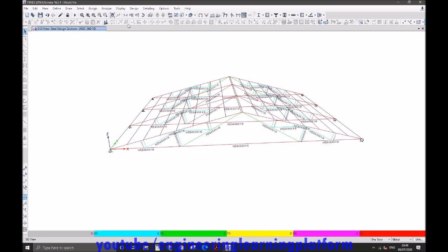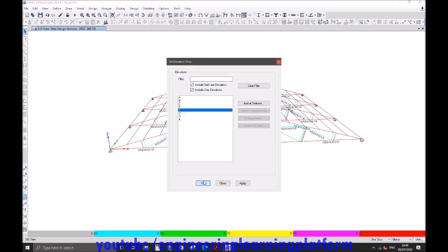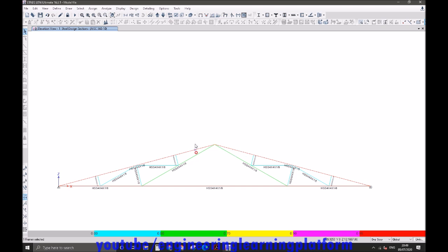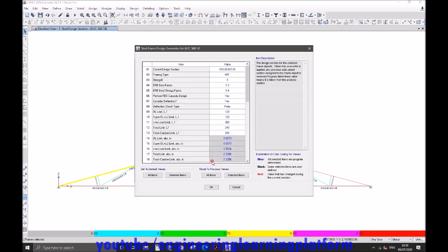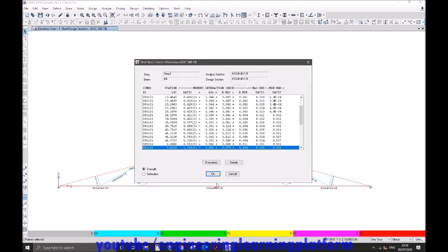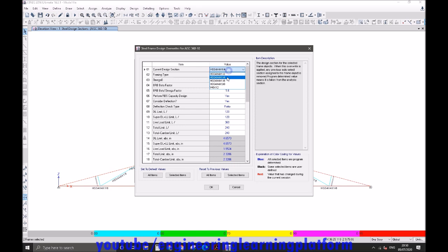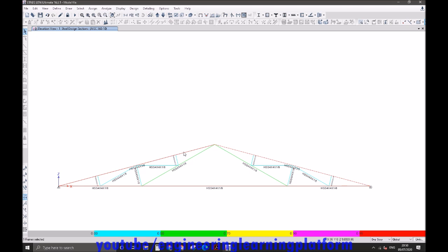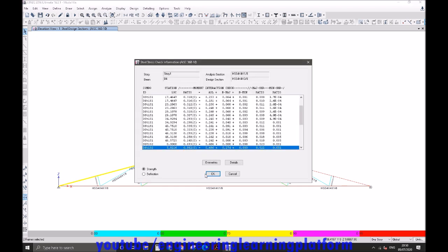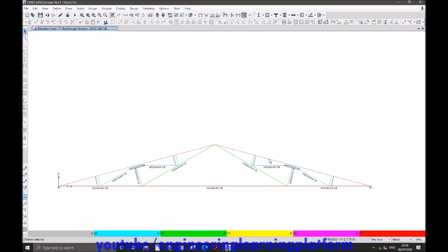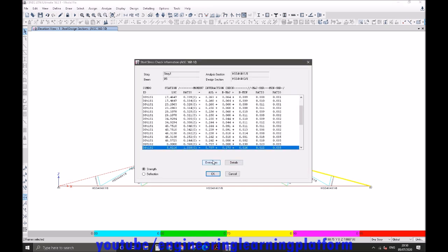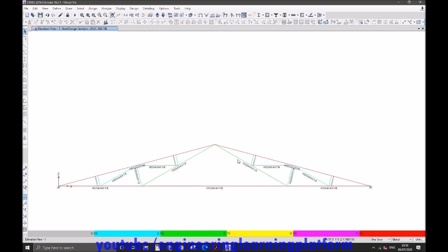It's a 2.4 stress ratio, that is a high ratio, so we need a bigger cross section for the top chord, bottom chord and the bracings. Let's try to override the member sizes and see if they pass. Let's increase the thickness of the wall of the tube. Still it has reduced considerably, but not passing the check. I suppose it would have passed now. Yeah, so it's 0.92 for the external truss.